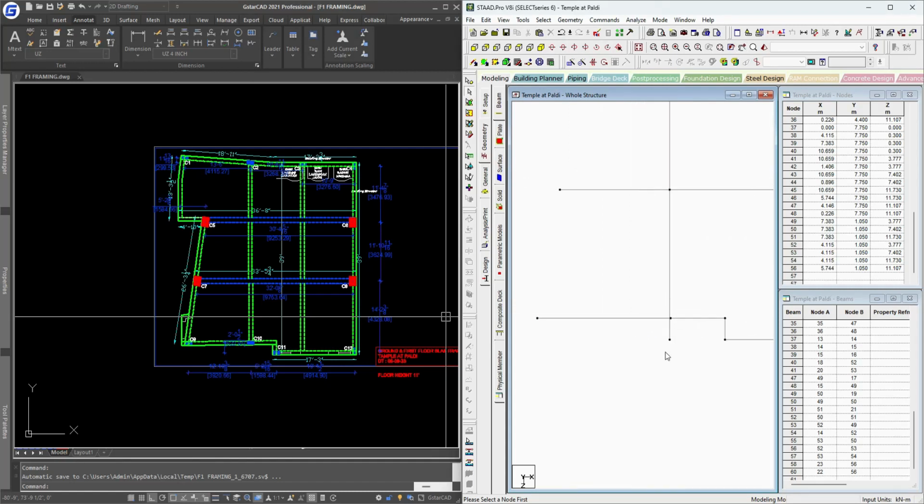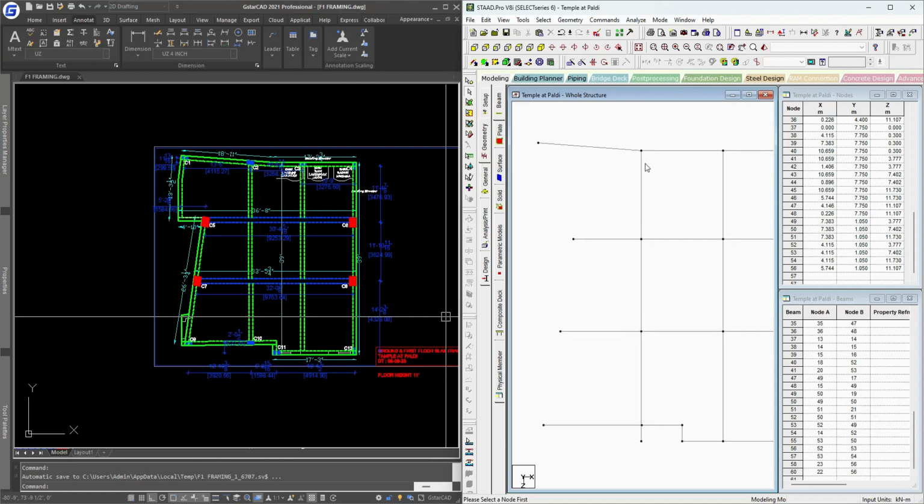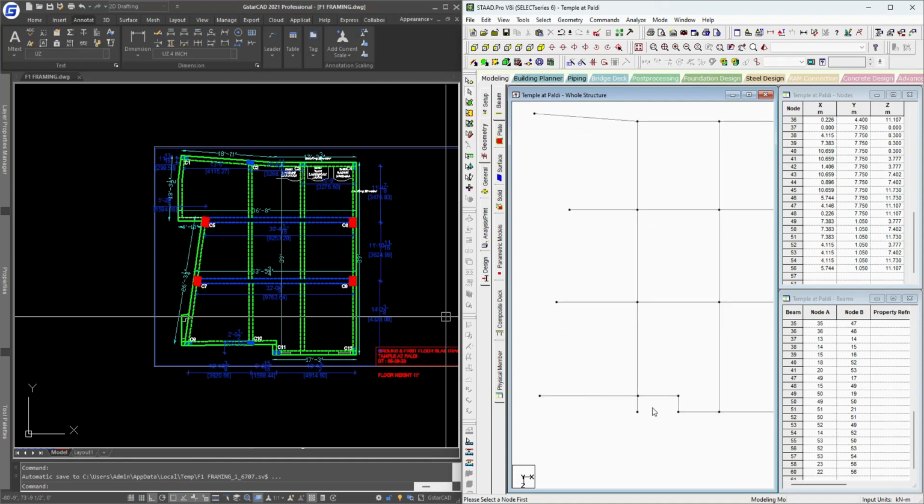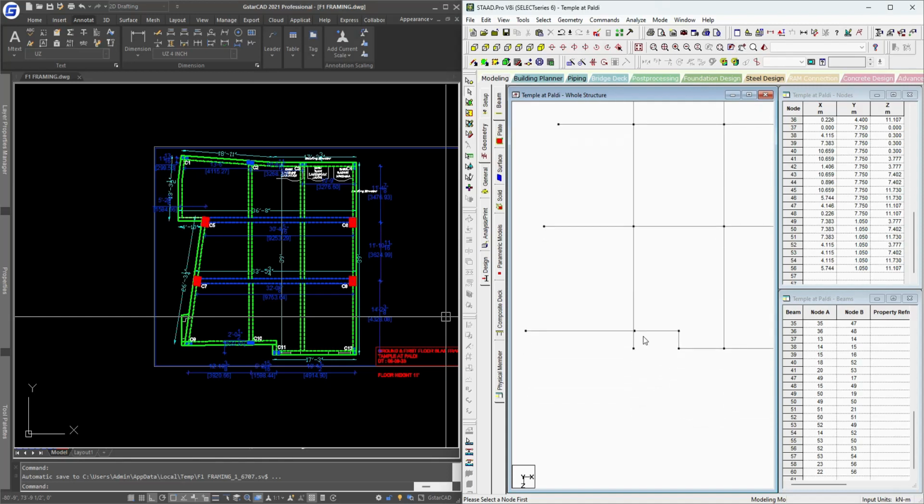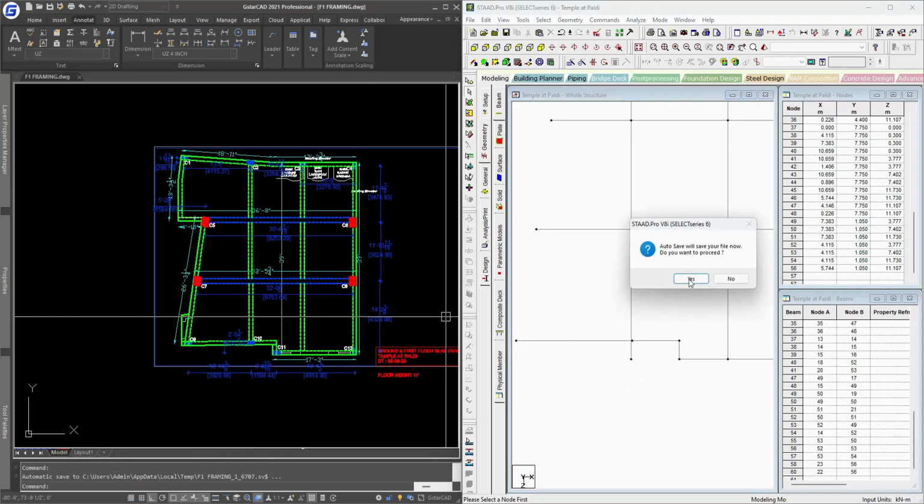The same way I have to draw this beam again, because this is not coming in the perpendicular direction, as both the column centers are a bit different, we can say. Ideally it should not have been like that way. We have two options for that. We can shift the column towards left to that beam, or we can just put the beam at the junction at where it is coming.